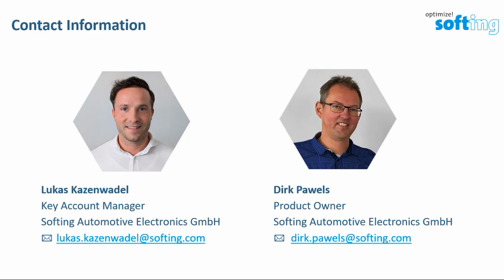That means you just take a USB stick, put it on the TCS device, and if you prepare the TCS device with TCS admin, then the TCS device writes the communication, either by CAN, CAN FD, or Ethernet, to the device. Later on, you can create a simulation based on this imported trace.